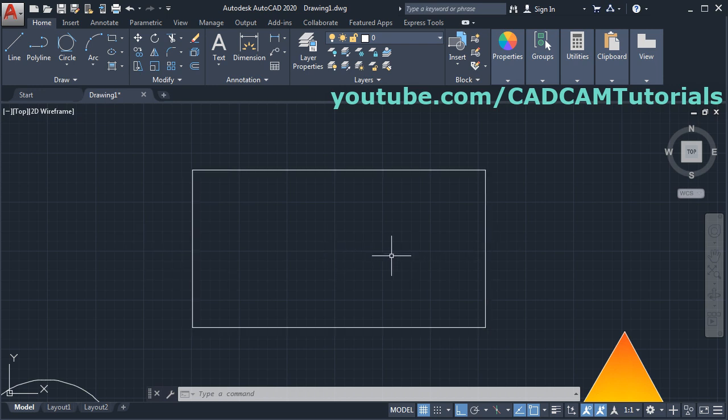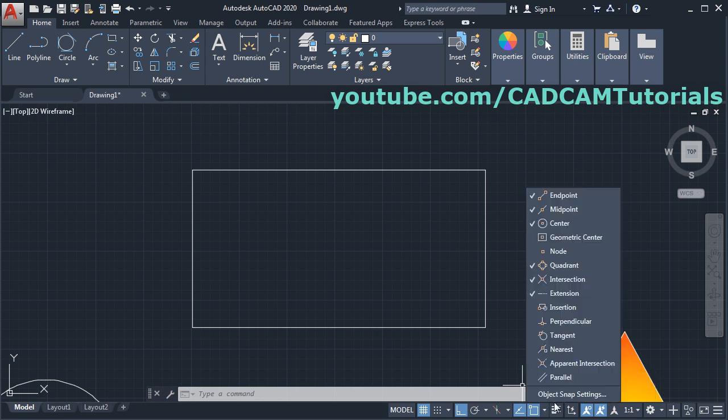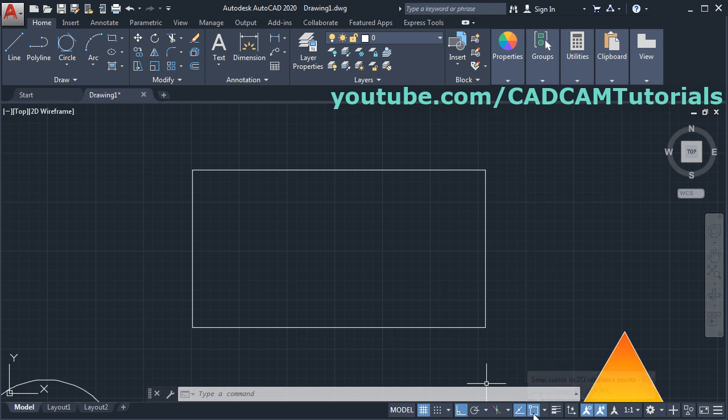Now for object snap tracking you will have to keep object snap tracking on. When it is on, it is visible in blue color. And you will also have to keep object snap on. Then click on this arrow and tick the object snaps which you want to use for tracking. So if you have all these settings done perfectly, then it will work properly. If any one of them is turned off, then it will not work.